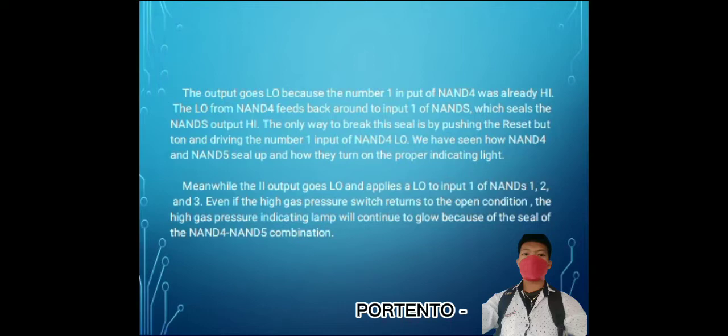The low from the 90 feedback around the 2 input of one of the NANDs seals the NAND's output high. The only way to break this seal is by pushing the reset button and driving the number 1 input of 94 low. We have seen how 94 and 95 seal up and how they turn on the proper indicating light.